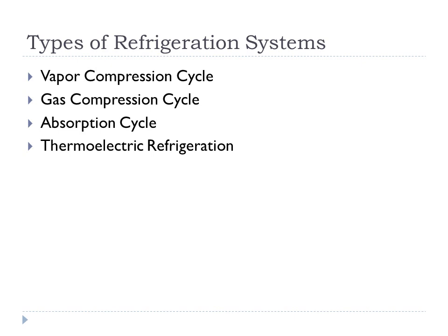It does not change into vapor or liquid phase. Absorption cycle involves a refrigerant which is mixed into liquid and then it is compressed. Thermoelectric refrigeration system involves passage of current through two dissimilar metal wires.